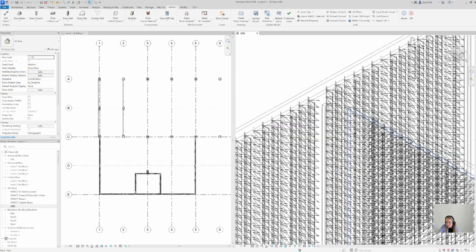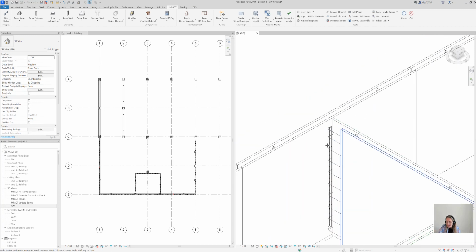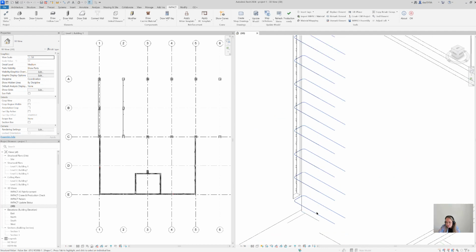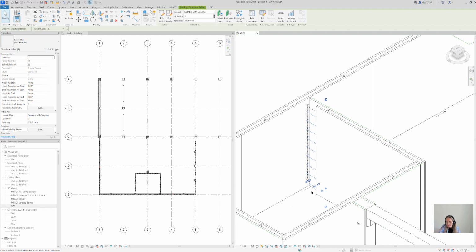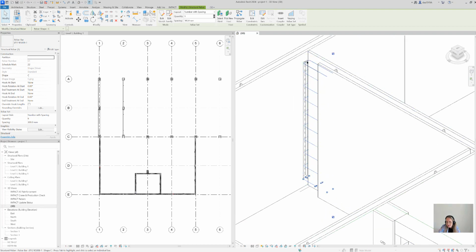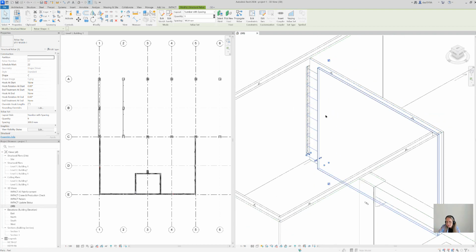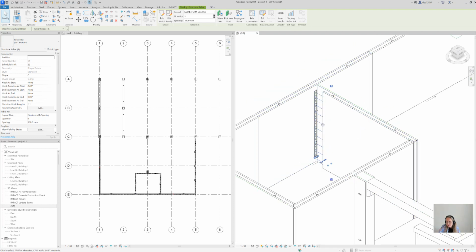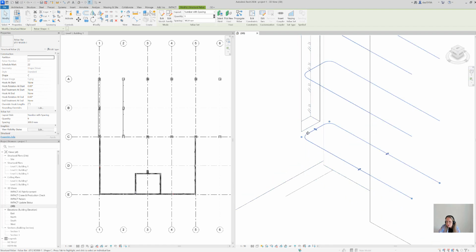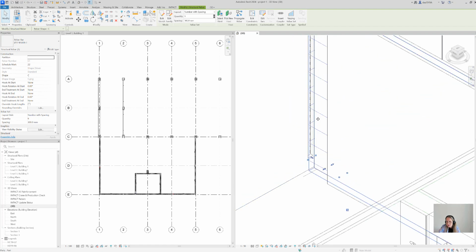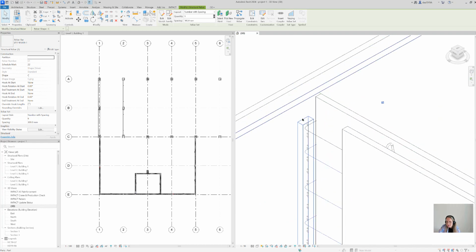Can we go to wireframe? Oh, it's not a good idea. Here, probably that's the best we can do in the 3D here. We can see the reinforcement is inserted. So yeah, you can see several clicks of the mouse and we have all those components inserting, including the holes to 200 millimeter from bottom and top. And remember, from Q1 release, we opened also that this hole can go all the way up.